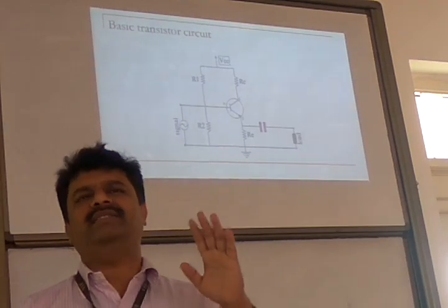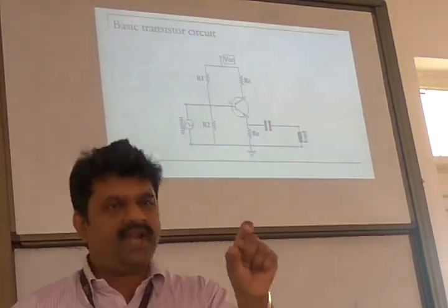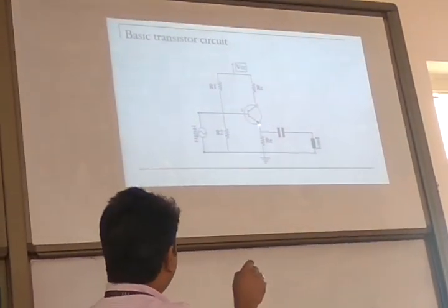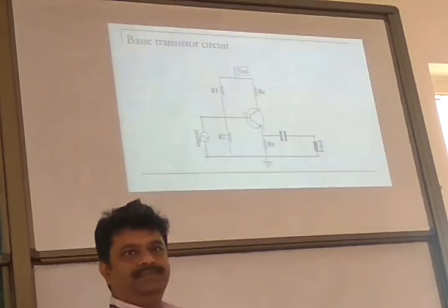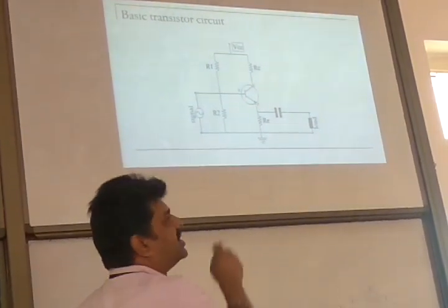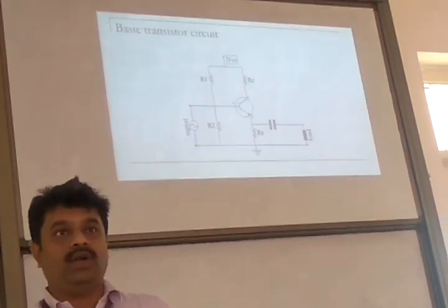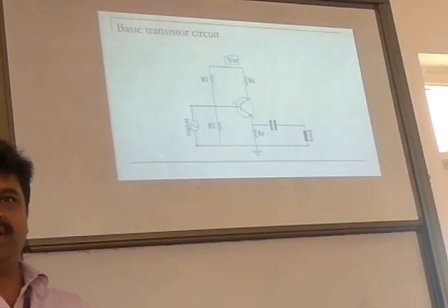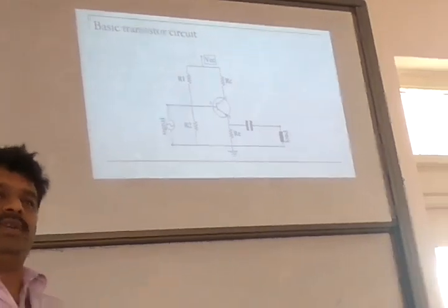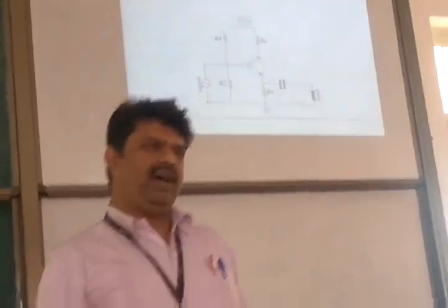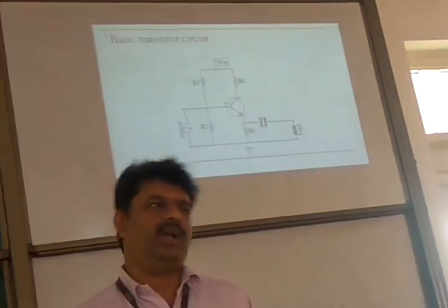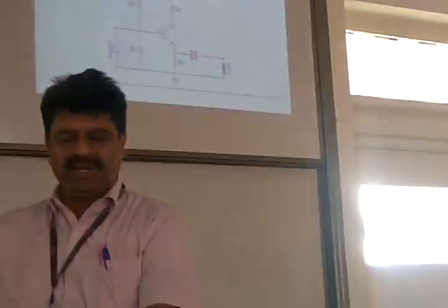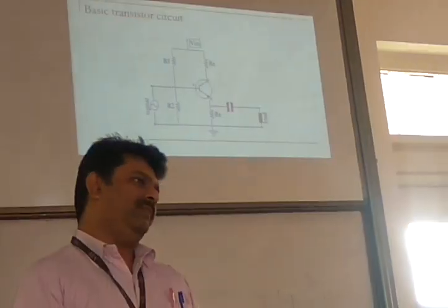Okay, exactly the same principle in the electrical domain. You create a potential difference by putting a standard resistance there, and then measure the potential here with respect to here. I want to know what the potential is here, what the voltage is there with respect to ground. Okay, so put a resistor. Anyway, the other end is connected to ground. Ground means zero potential. With respect to that, what is that potential you measure? People get used to it, the people who are in the electrical domain. If you want to measure current, simply cut the wire. One end you connect to one end of the ammeter, the other end you connect to the other end of the ammeter. You can measure the current.